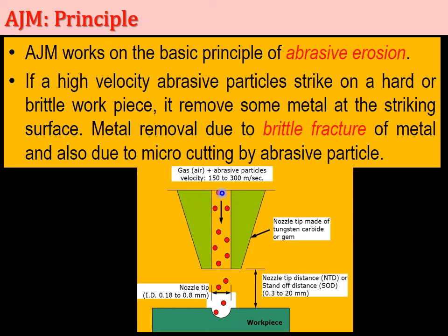All the abrasives come from this nozzle to form one jet across this standoff distance, and this jet impacts the workpiece surface. The workpiece surface undergoes brittle fracture. The abrasive makes cracks on the surface, and the abrasive also removes the material in the form of abrasive erosion.